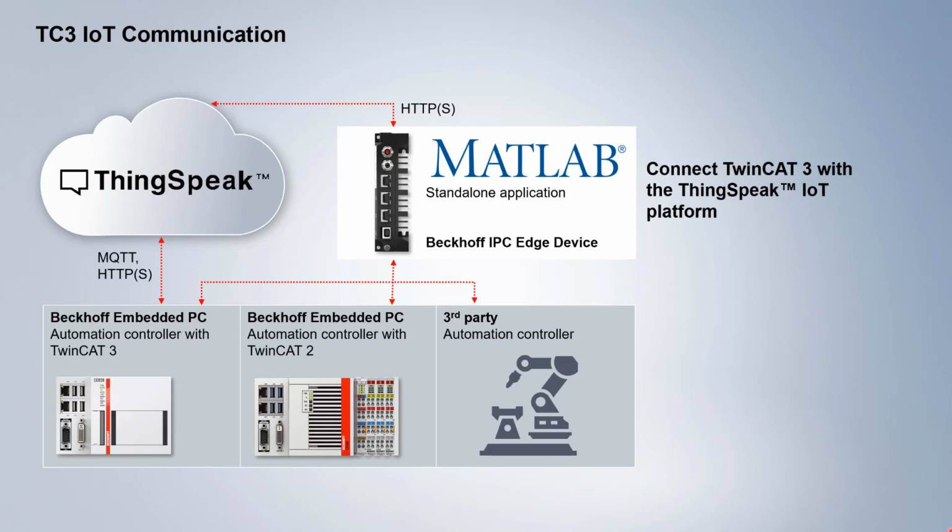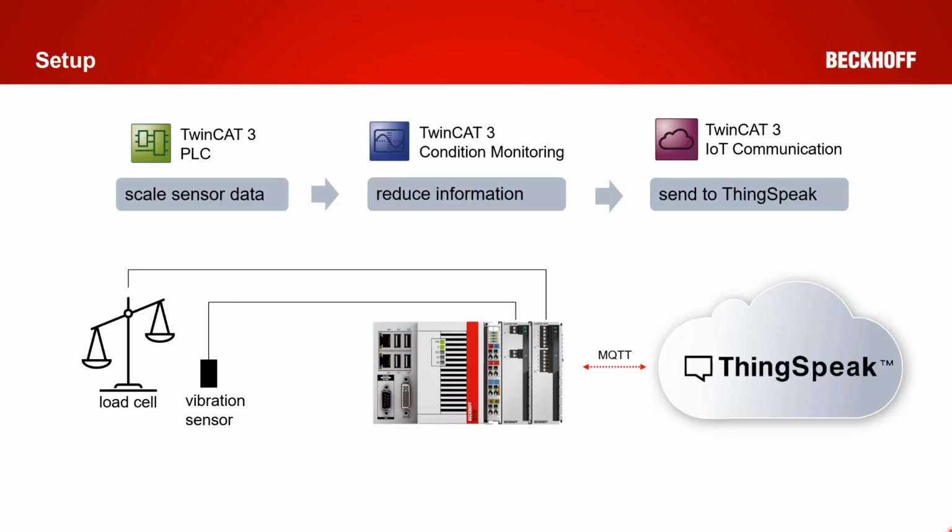Let's have a closer look at our IoT scenario. We have a Beckhoff embedded controller, and attached we have two types of terminals. One terminal is to interface with a load cell, so the terminal realizes a full bridge, and we have a vibration sensor connected to the other terminal to realize an IEPE interface. The load cell is of course for weighing applications, and the vibration sensor is for observation of disturbing vibrations on